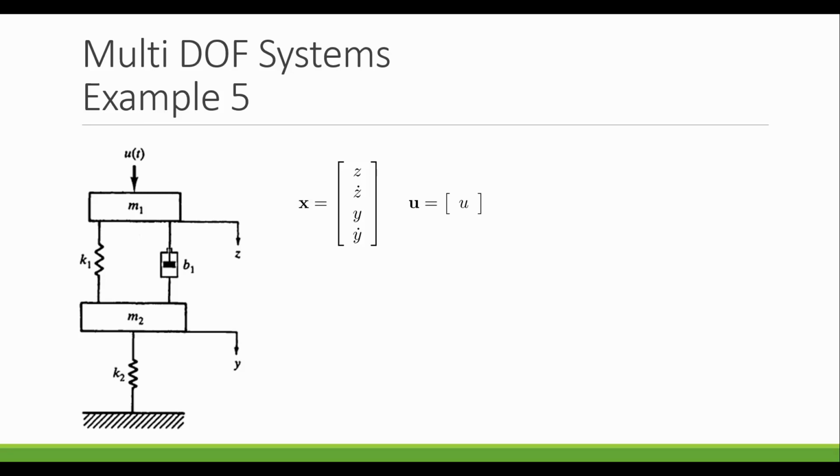It's going to be important to note through the analysis here that we have a 2 degree of freedom system. However, there's only a single input and it's acting just on m1. If this system were to have an input on m1 and m2, the analysis we are going to do from here is not going to hold up. So the fact that it was one sinusoidal input, we can use a Bode diagram in a very similar way to how we did it when we were looking at 1 degree of freedom systems before.